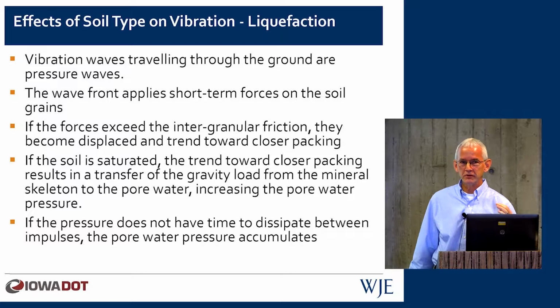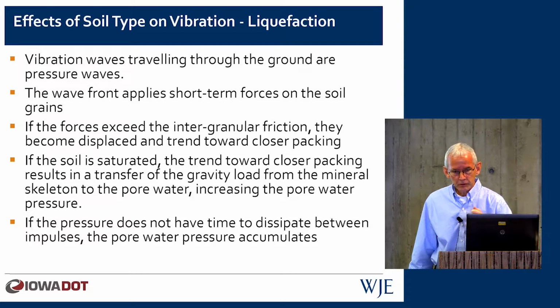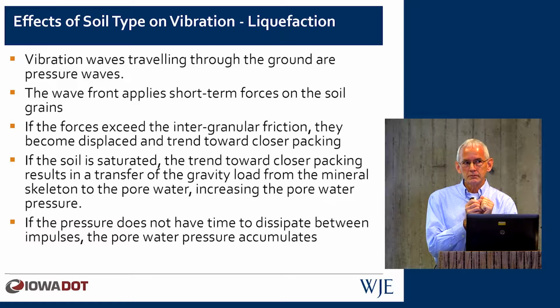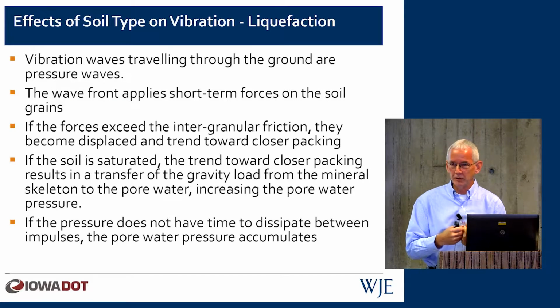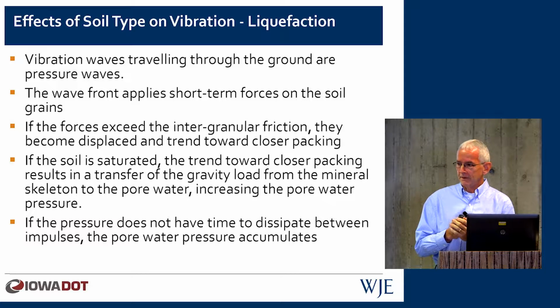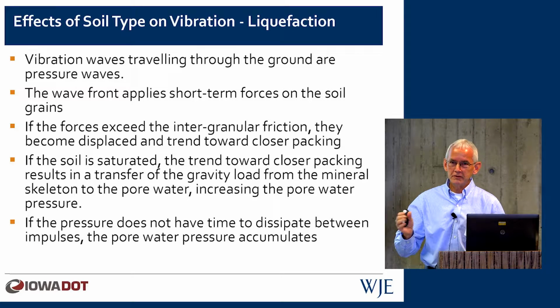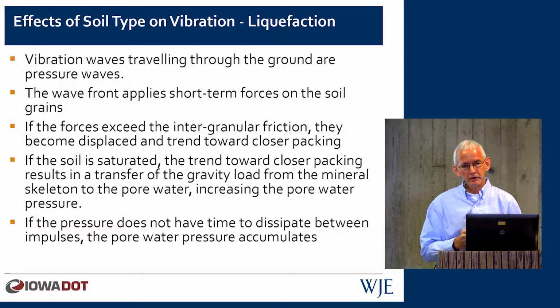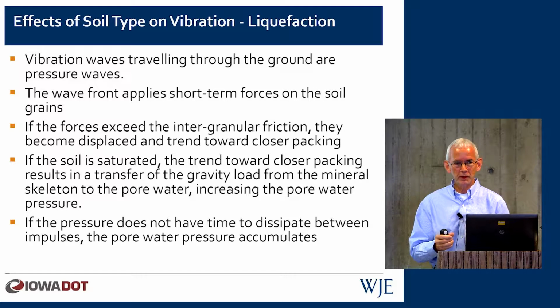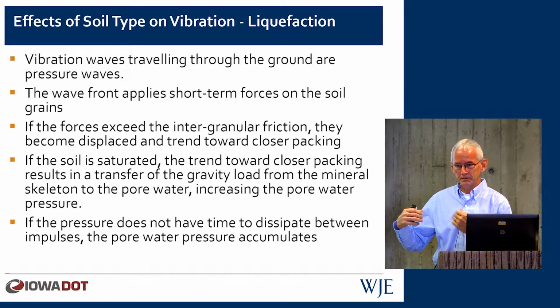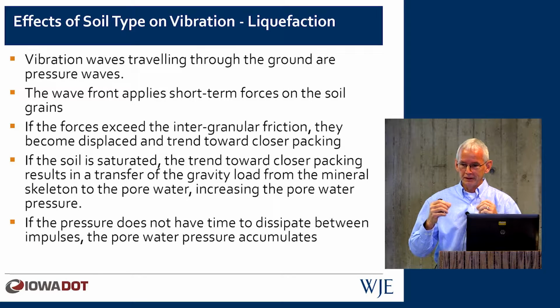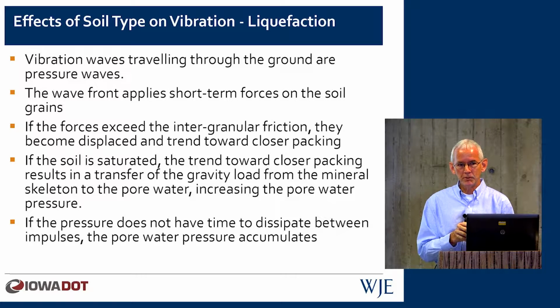Each impact or each cycle of vibration will produce a pressure pulse that tries to push the grains apart because it's applying this pore water pressure between the grains. It pushes the grains apart, and each successive cycle tends to add to that if they occur too frequently. There is some time that is required for that pore pressure to dissipate. Sometimes it can be a matter of minutes. You're introducing a pulse into the ground, into the pore water, and you get a sudden rise in pore pressure even with the first cycle of energy.